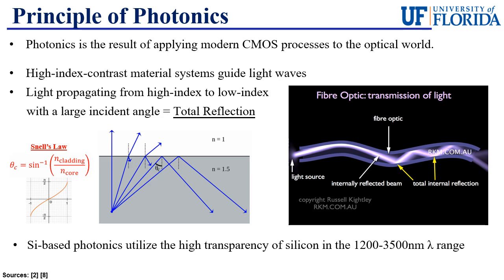If we make clever material choices to minimize the critical angle, these photons that would normally only partially reflect could totally internally reflect and remain within the core of the waveguide. Now, ideally, we want all photons to totally internally reflect. So by minimizing the critical incident angle, a photon interacting with the cladding will have more incident angle modes that achieve total internal reflection.